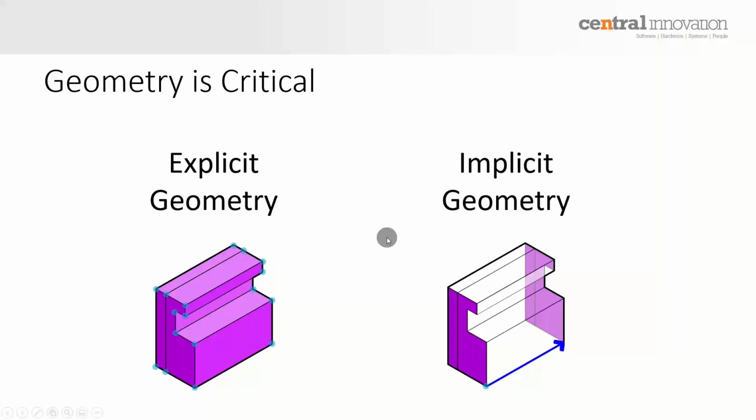Now, in the case of Archicad and Revit or Allplan or Vectorworks or EcoSim or the other, this implicit geometry is very common because it is based on the productive tools that you use. Think of it as typical walls or beams. They're good examples of extrusions along a vector, but also planar things like slabs or roofs.